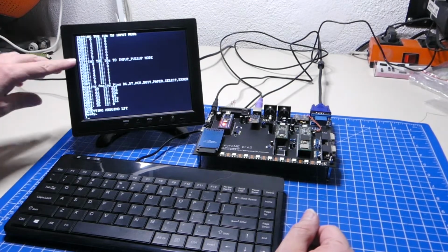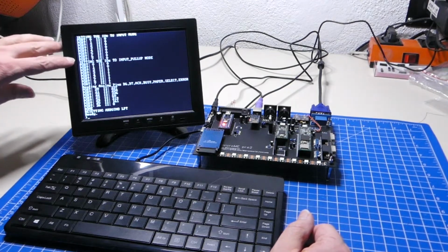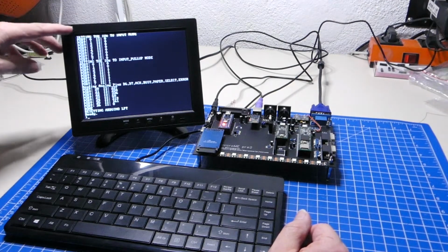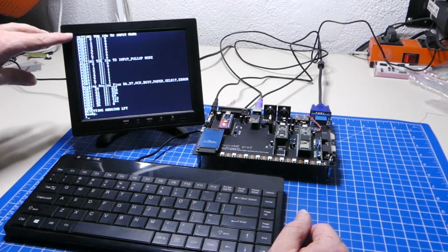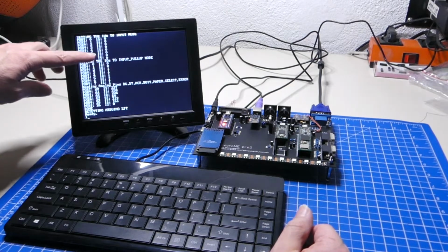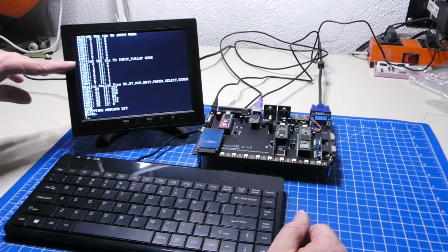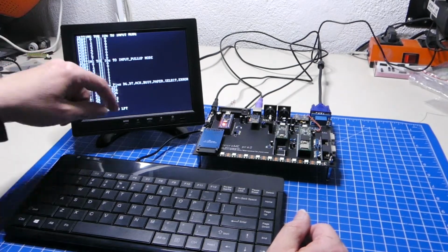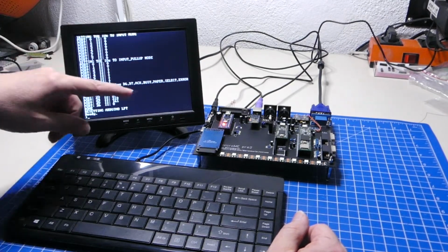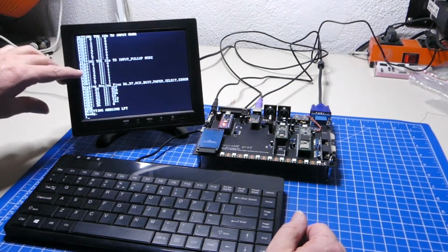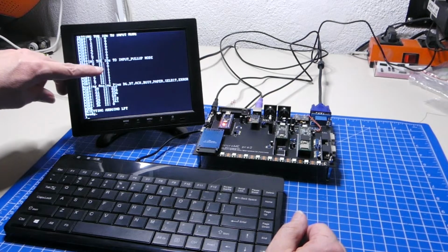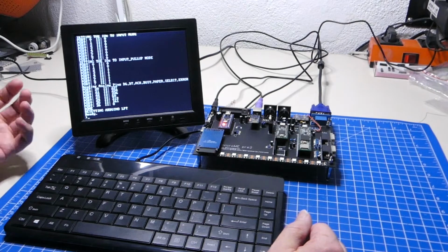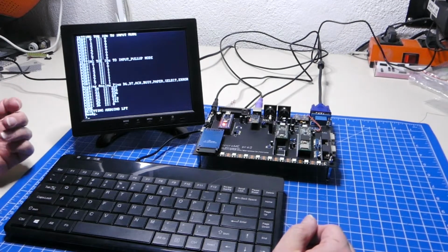And if I set the ports, I can actually see what they're doing, and I can query the ports. So I have the ports set on input mode right here, so I can see all the ports are now at 0. Then I can set to input pull-up mode, and because there are 2 LEDs on those 2 ports back there, I can actually see that port 0 and 1 are being dragged down by those LEDs, which makes me see that the input is working.